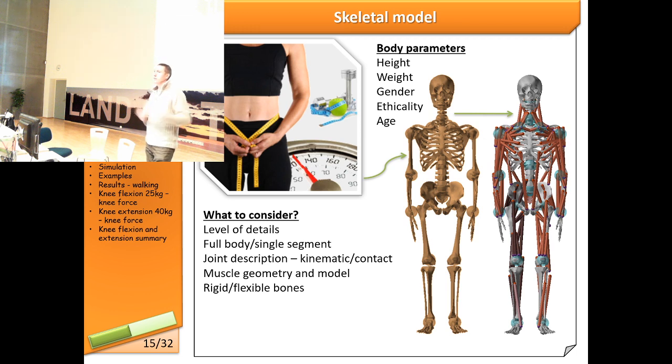Sometimes it's not worth taking the full body if you just make a motion of a hand, for example, or the leg in some support. Then the whole body is a kind of overkill. Unless you know how to do it efficiently, then of course it's fine. But if you're just experimenting, try with a small part. If you try to simulate a hand, just take the hand and try with one finger. After you get one finger working, add another one and another one, because otherwise you might get into more problems in solving what is not working in the simulation than actually doing the simulation.